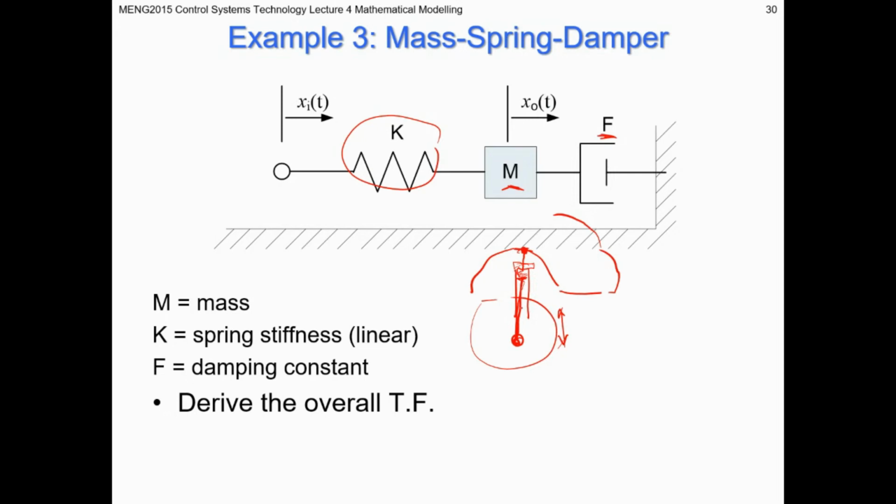So as the wheel hits a hole or hits a lump in the road, or a speed hump or something, then the wheel's forced upwards, but the rate of motion of the wheel is slowed down by the damper. And that's the same as what's represented here, right? That's what is shown with this ram and a cup shape. So this is really showing a piston, a hydraulic piston, which is what the damper is.